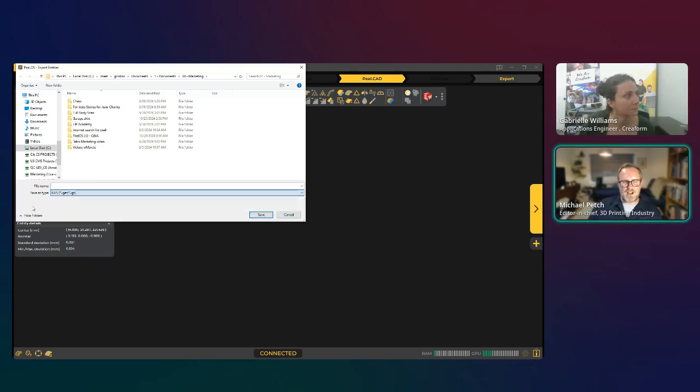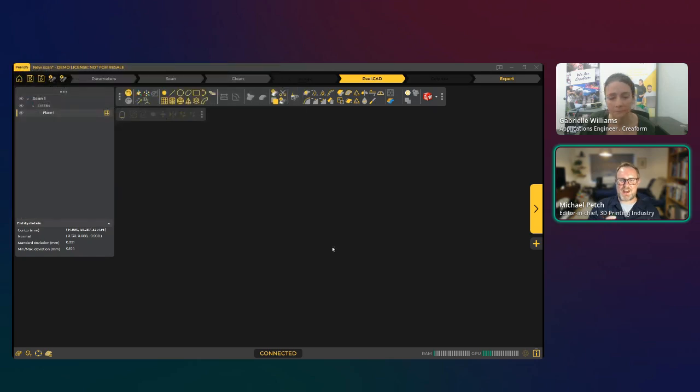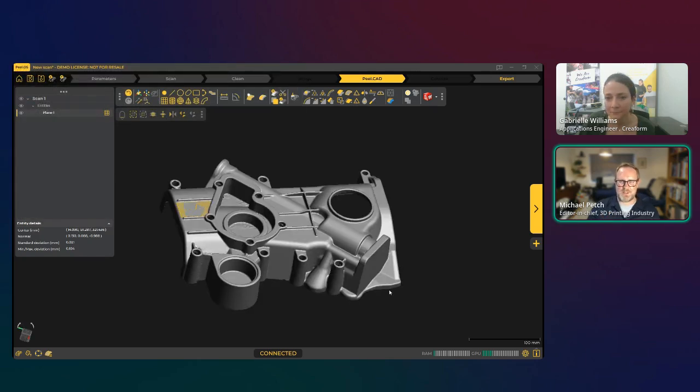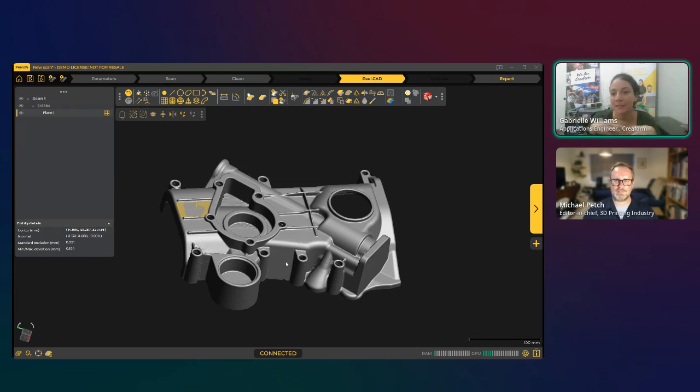So I wonder, you've been doing this for a while now. What are some unexpected ways customers have incorporated 3D scanning into their business? Oh, this is really fun. Okay, so there are so many different things you could do. You can do reverse engineering, where you're just creating a CAD based off of your scan. But a lot of big companies will also scan a part and compare it to a CAD. You bring a CAD, overlay it with your scan, and then you can see a color map comparison of the part.